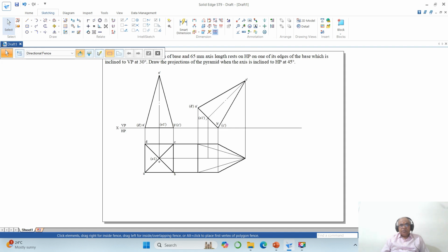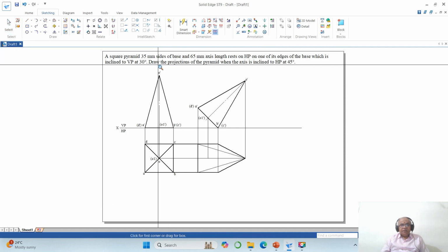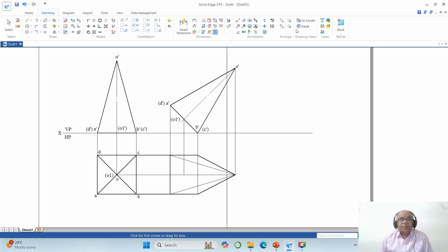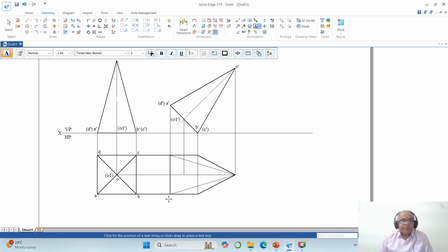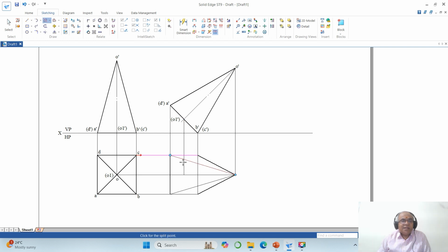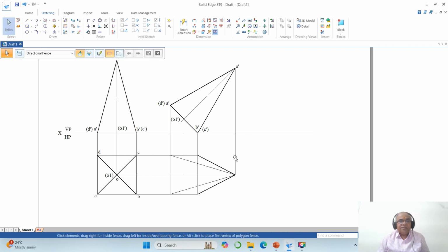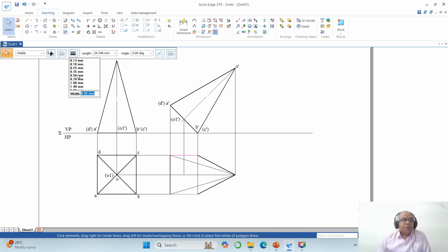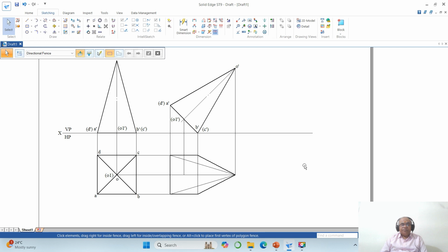Now once you do that, the surface which is near to the observer is visible. Which is the surface we are talking about? Before that, first I am going to mention the names of the text. Now here, first I will go for this line, and this line I make it 0.05 first. Okay. Now I will go for split this line till here. Then you split this line till here. Now we go for select this line and this line. Both are the exterior edges of the boundaries of the solids. So now you make it thin.